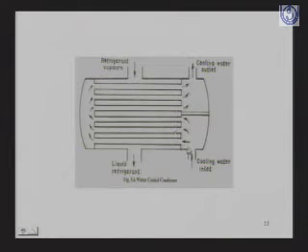This water has chilled the vapors, they have been converted into liquid refrigerant, and then the condensing water is going to the outlet. So this is the cooling water inlet, the condensing water outlet, the refrigerant vapors inlet and the liquid refrigerant outlet. This is known as the water-cooled condenser.